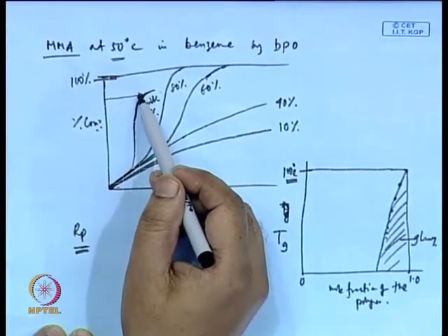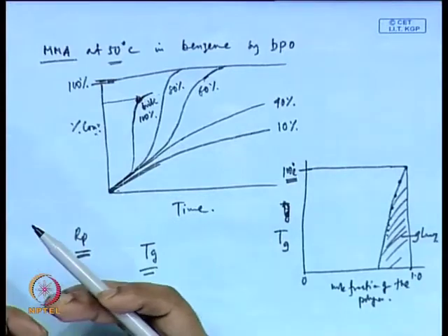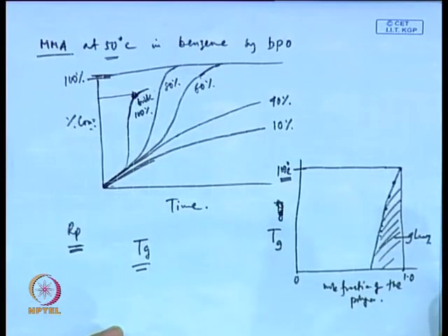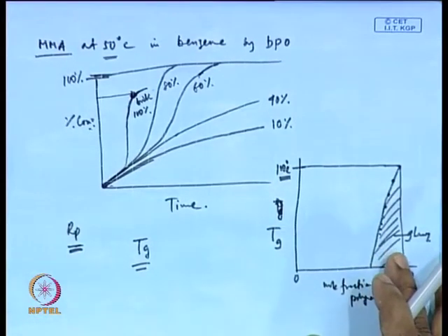Okay. So, once the polymer becomes glassy, then the polymer chain, the kinetic chain, cannot participate in the reaction and cannot make new polymers. So, in the glassy region, below the glass transition, it cannot participate in further polymerization.